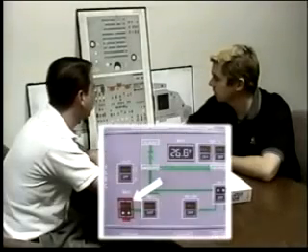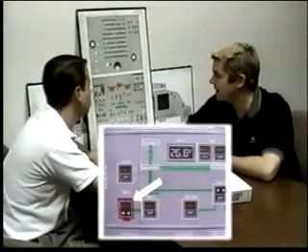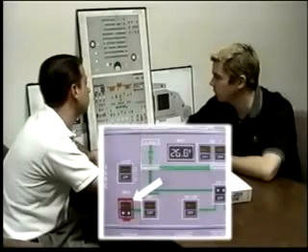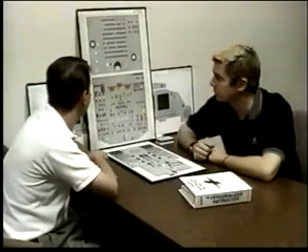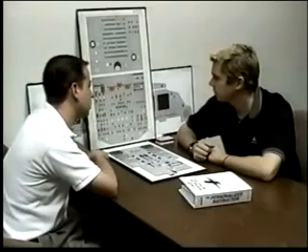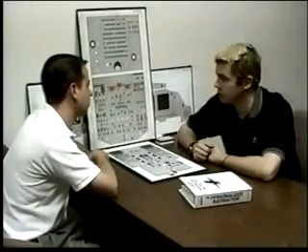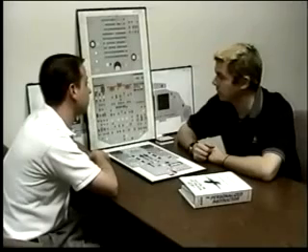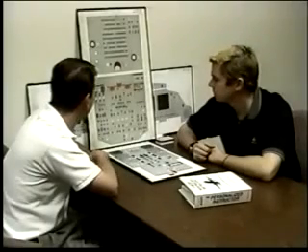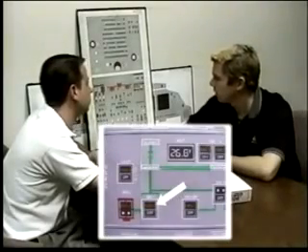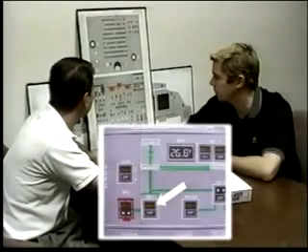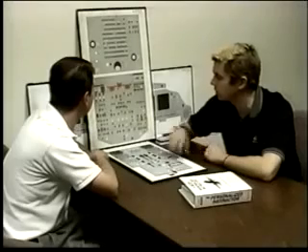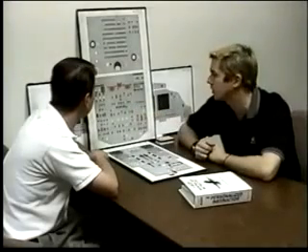Fault in IDG. IDG fault means that the IDG oil temperature or oil pressure is abnormal: the temperature is high or the pressure is low. Any cautions to selecting an IDG? Yeah, don't press it for more than 3 seconds, and don't press it if the engine's not turning. Fault on Gen 1. Indicates that the GCU has detected a protection fault, or the line contactor is not closed and the switch is commanded it to close.